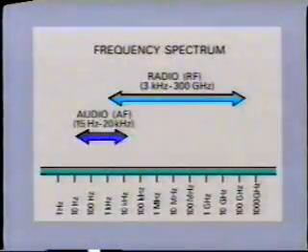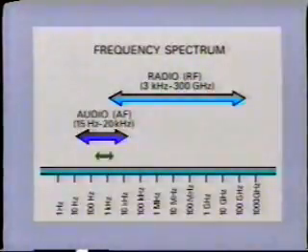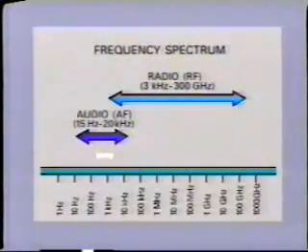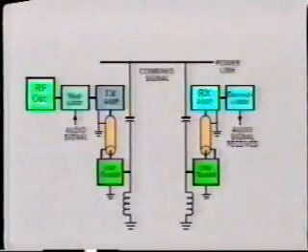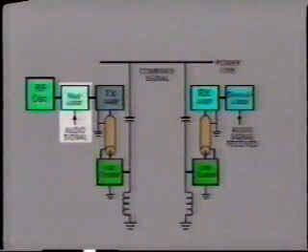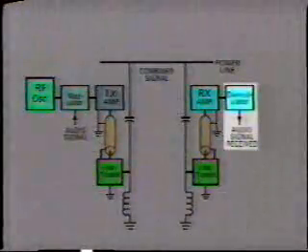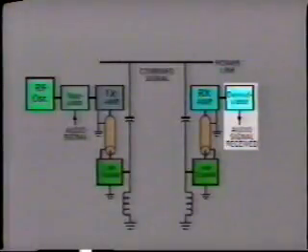Signals such as voice and telemetry all operate within the audio frequency band, usually between 300 Hertz to 3,000 Hertz, or 0.3 to 3 kilohertz in relation to the carrier signal. This audio signal is mixed with the RF carrier signal in a modulator before transmission down the line. The mixed signal is then demodulated in the receiver at the other end, leaving only the audio signal.